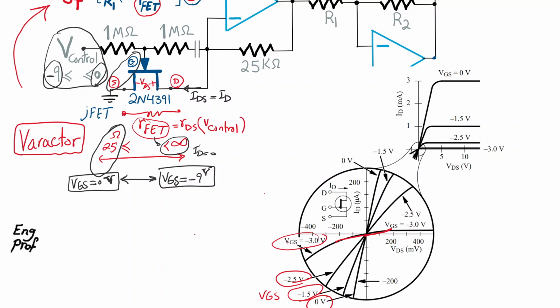And if we keep decreasing VGS, there will be even less slope and more resistance, and at some point it will shut down the transistor, effectively equivalent to an infinite resistor. So with that said, we are just working in this region in a very small VDS range, which is good enough for us, in the deep linear region of the N-channel JFET.